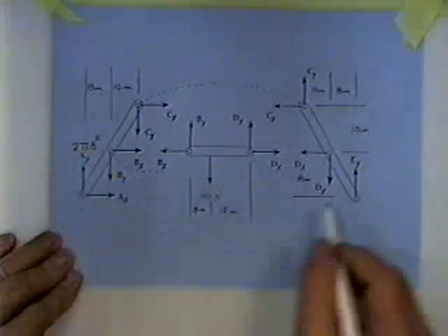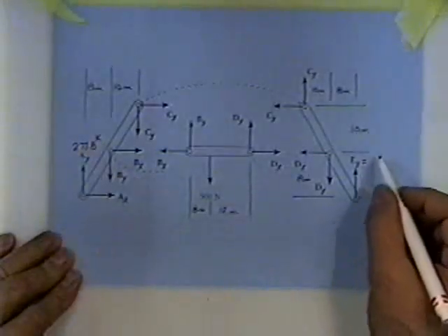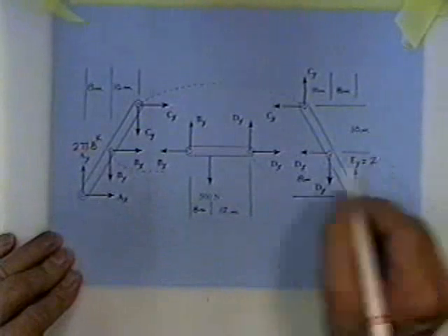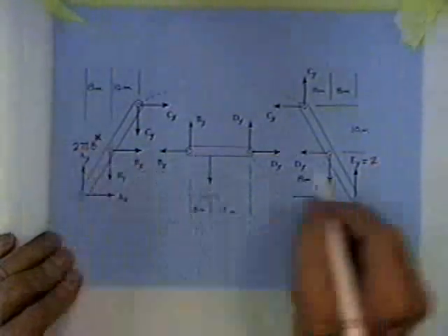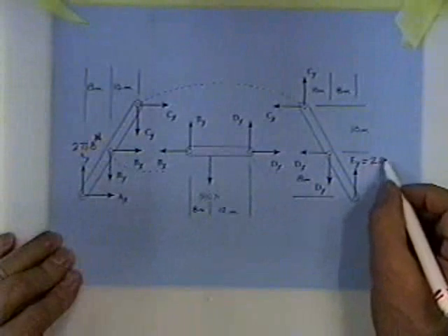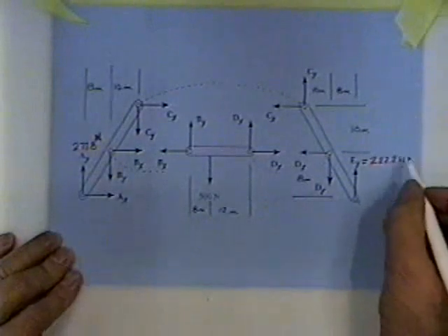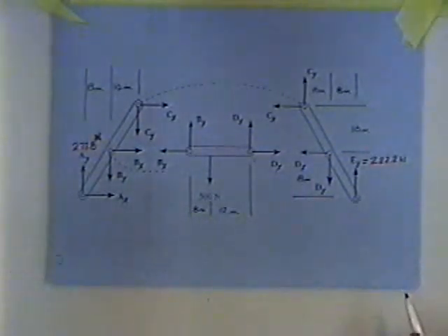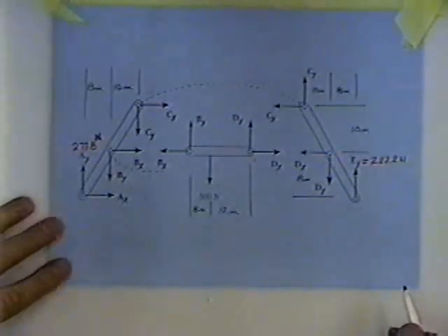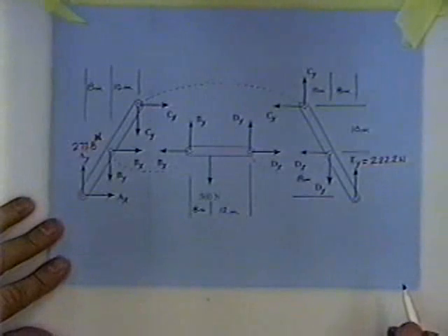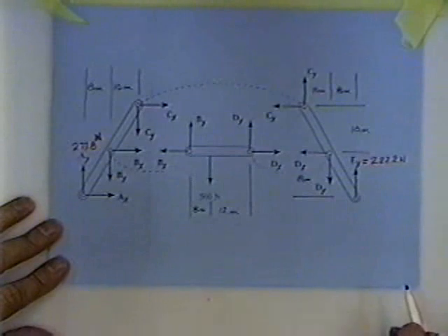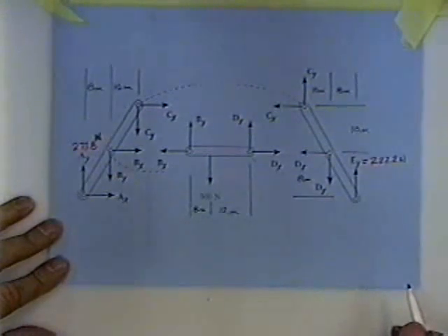7.8 kips. And we know the magnitude of EY is 220, oops, those aren't kips, those are newtons. 222.2 newtons. And that's all we know. Your best bet for answers is invariably a horizontal or a vertical member. You'll get answers quicker by pulling that piece out for first consideration than if you pick a slanted member.